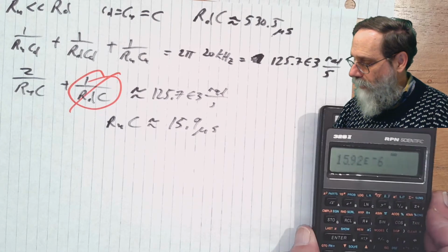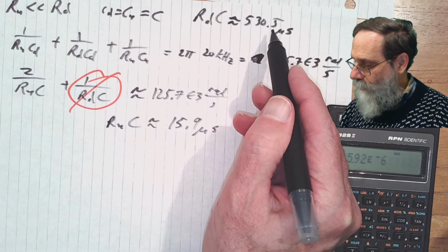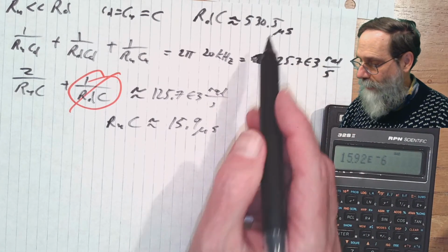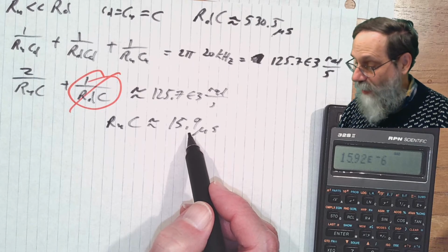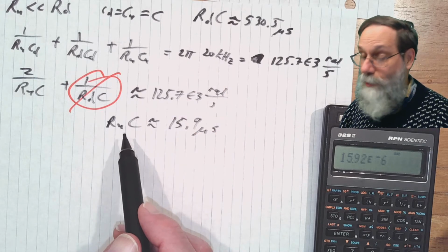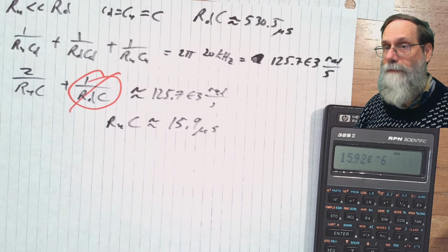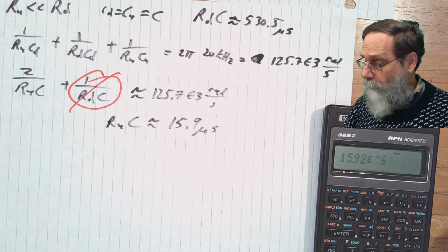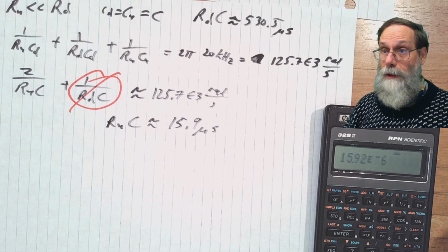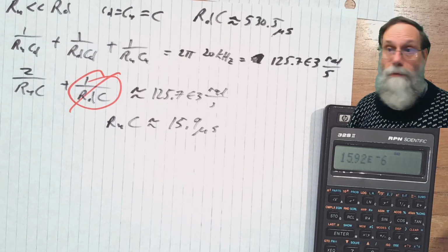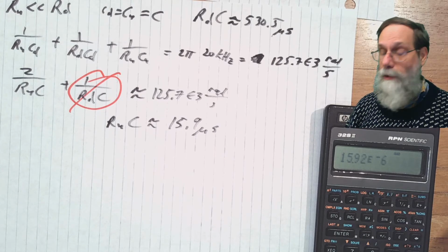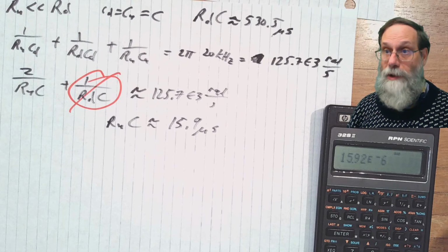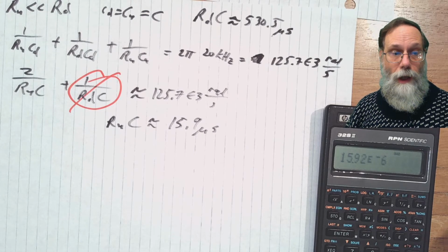All right, now if we look at the ratio of RDC and RUC, 530 over 15, that is, RD is very much larger than RU, so we're still meeting that constraint. We haven't cheated here. Now we need to just pick a value for C in order to get reasonable capacitor and resistor values and then check to make sure that all of our calculations are right.